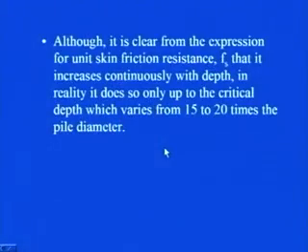Although it is clear from the expression that the unit skin friction resistance Fs increases continuously with depth, in reality it does so only up to the critical depth, which varies from 15 to 20 times the pile diameter. So, the critical depth concept which I explained earlier is valid for this determination of unit skin friction resistance along with the unit point bearing resistance. Exactly in a similar manner as we took care in case of point bearing resistance of this critical depth concept, we have to take care here in this case of unit skin friction resistance.